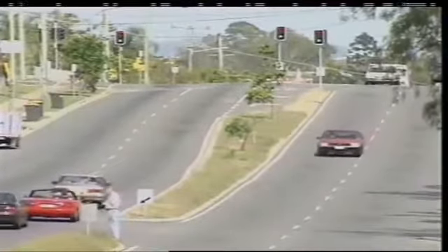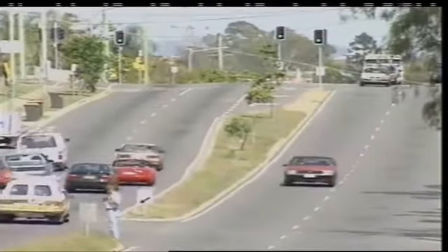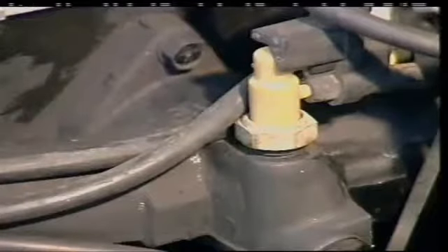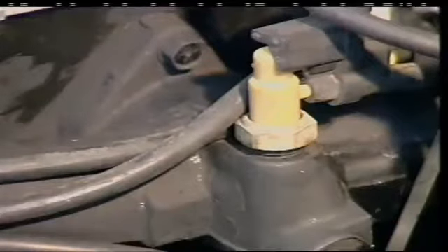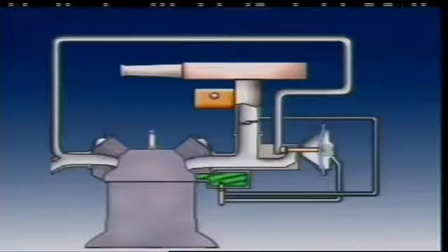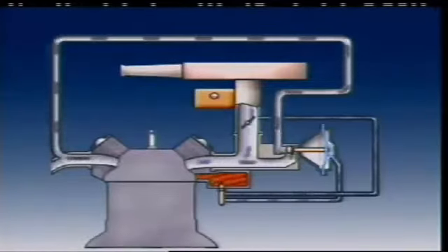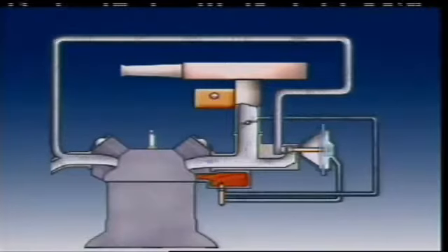The EGR valve usually opens when the engine is at normal operating temperature and likely to be using a lean mixture. When the engine first starts, and until it warms up, a temperature-sensitive valve prevents manifold pressure reaching the EGR valve and stops it from operating. Manifold pressure reaches the valve when the engine is warm, and when the EGR port at the carburetor is influenced by the position of the throttle. This is generally at light throttle openings, when a lean mixture could cause increased oxides of nitrogen. It does not operate at idle or at wide open throttle.